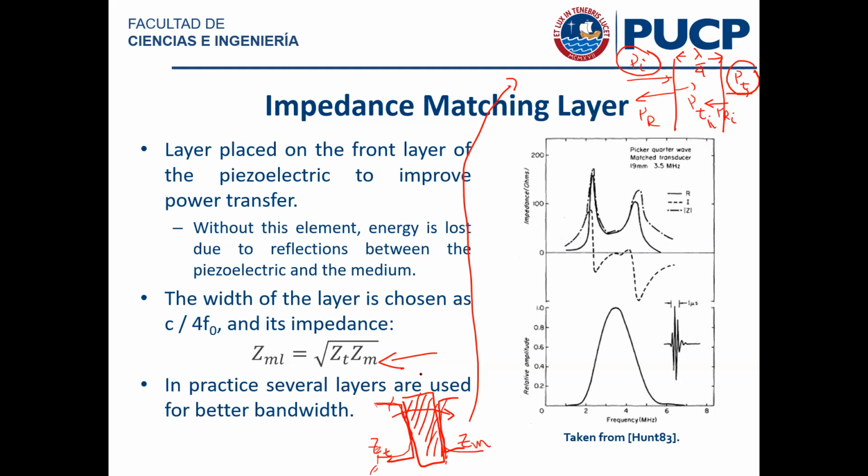Now, that condition itself, the impedance of the matching layer, fine. I mean, with sufficient handling of the materials, people have devised ways of modifying the impedance of the layers or the material that will make the layer. The tricky part is the thickness, because by definition, the thickness is equal to the quarter part of a wavelength, but the wavelength is equal to the sound speed divided by the frequency, which means that technically speaking, the lambda over 4 matching layer only allows 1 frequency to be perfectly transmitted across the layer.